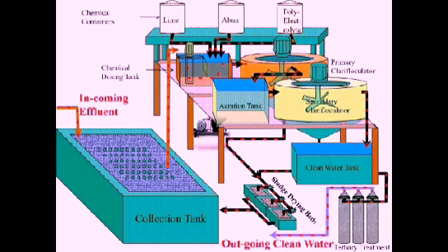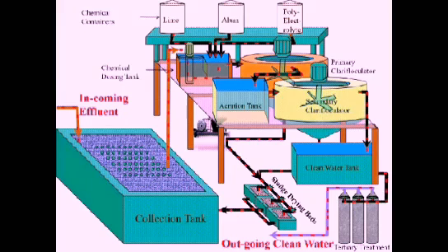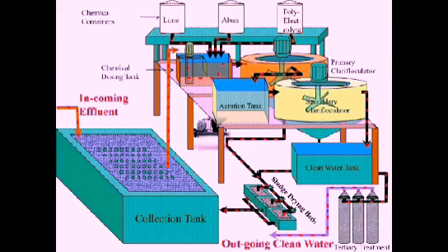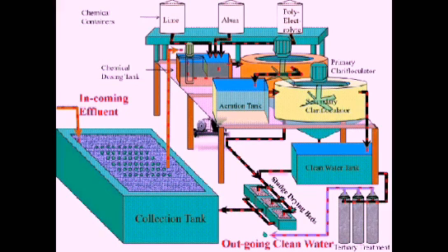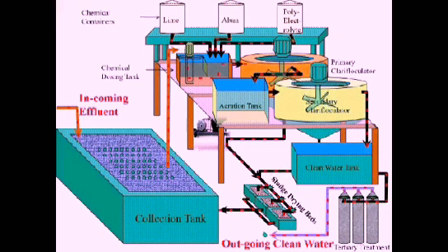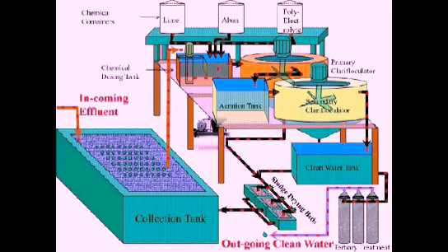As you can see from here, the collected water is pumped into the chemical dosing tank. In the chemical dosing tank, we first do the mechanical treatment. This has two parts. First, we create a baffle wall at the center of the dosing tank to separate the oil contents, if any, present in the effluent and stop it from going further in the system.